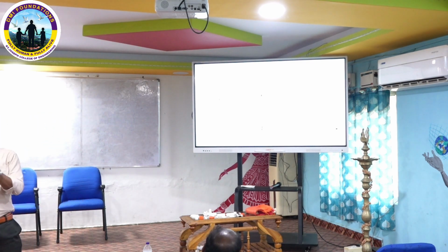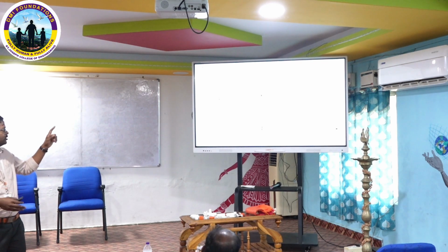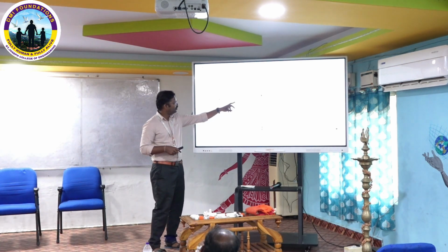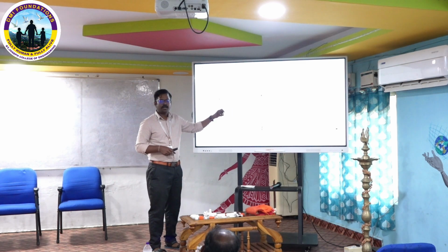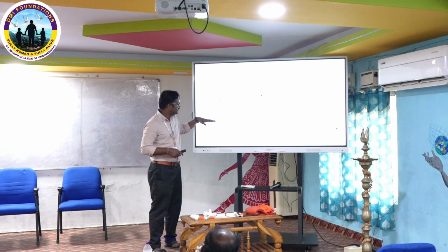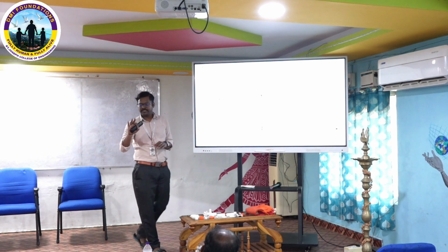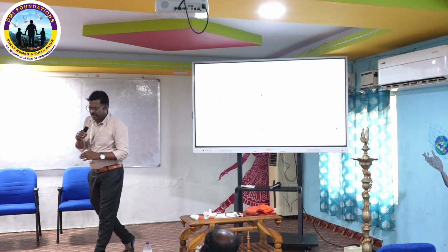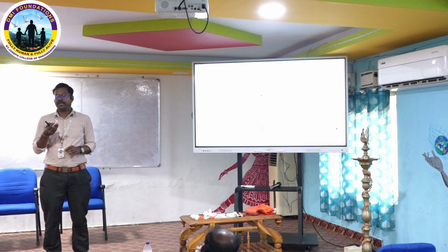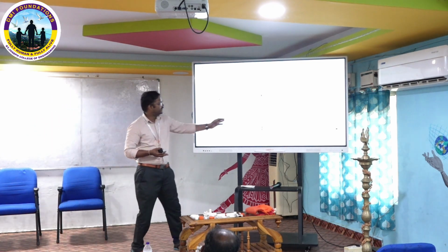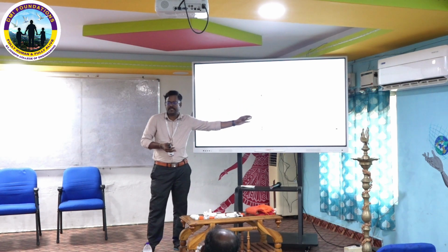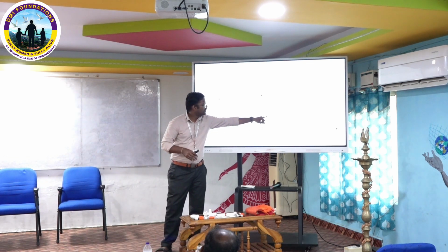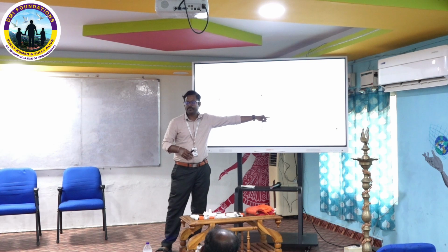I told you already about two kinds of structures: one is bending dominated, another is stretch dominated. Here, when you give a load to these bending dominated structures, they bend and absorb the energy with a smooth region. Actually, we have three regions of the stress-strain curve. First is the elastic region, in which if we remove the load, it comes back to its original position. But when it comes into the plastic region, it gets permanent deformation. But in comparison, we can see different kinds of responses.